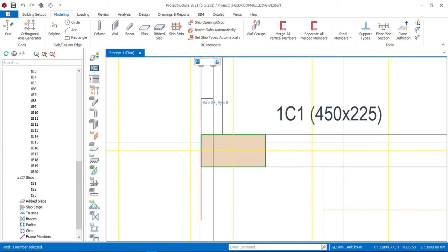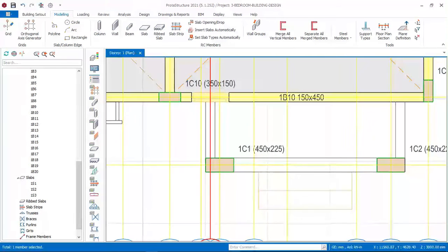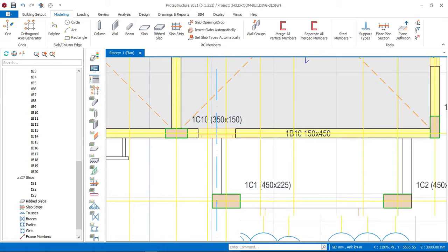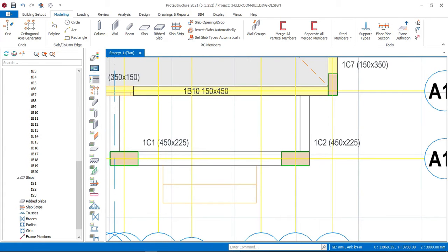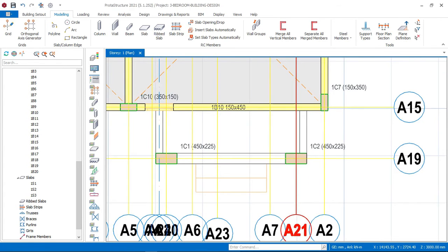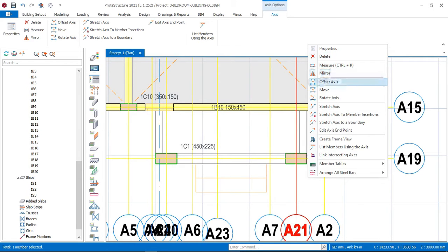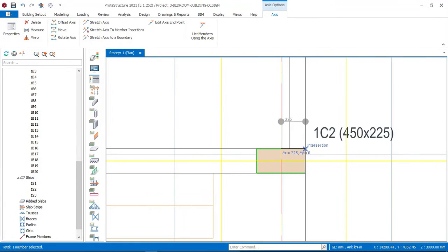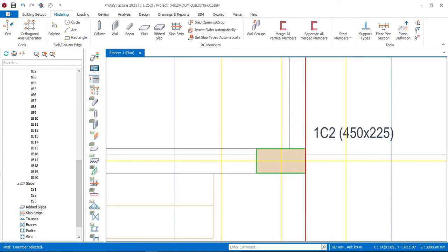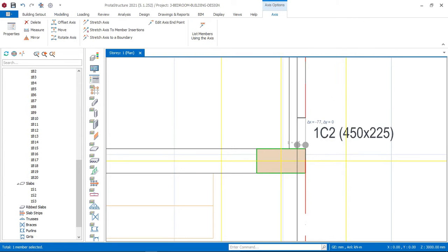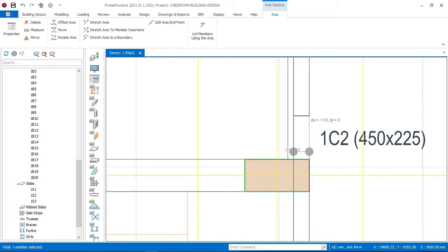75, which is half of the wall, and then click on enter. Okay, so we now have this at this very point here again. So I will now go here and do the same thing at this very point. Click at one of these axes and then say offset, and offset it to this very end. And at that point, I will now move this grid back by 75. Shift F2. Since I'm going inward, I'll say minus 75 and press enter.